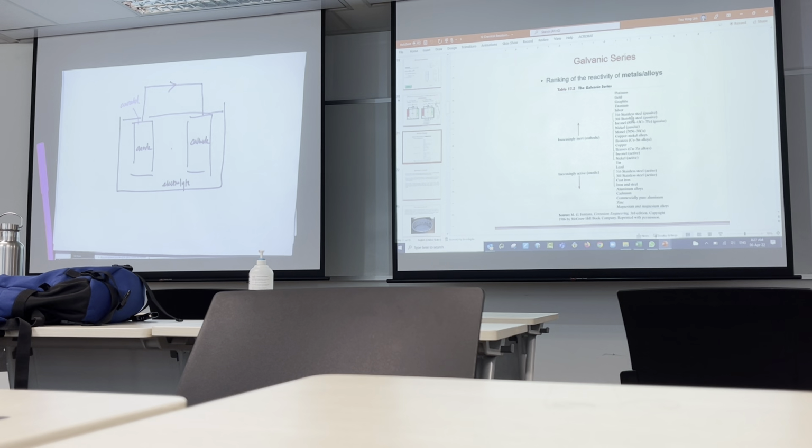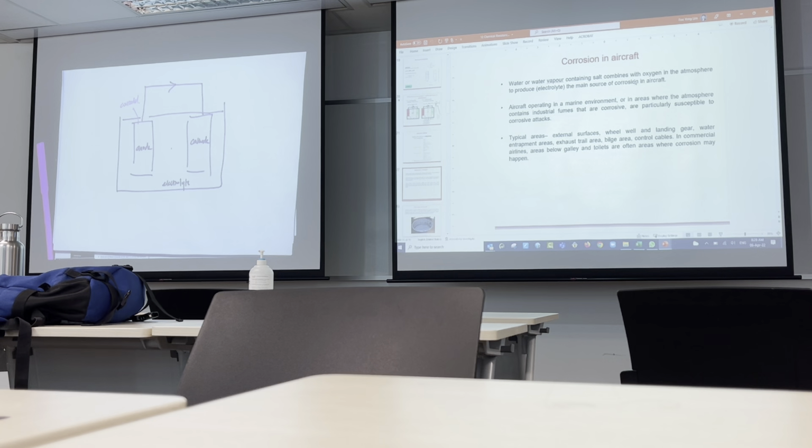Okay. So over here, galvanic series differs from the EMF series from a very simple idea. The concept is similar, but galvanic series focuses on engineering materials. EMF series is very good from the theory perspective, from a chemistry perspective, individual atoms. It's good to lead you to the theory, but not great in terms of relating to a real world application. So engineers, we look at galvanic series more. But in the absence of galvanic series, we can fall back on EMF series to predict certain things, especially on the pure side.